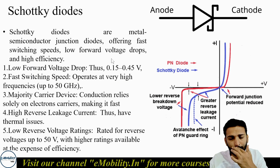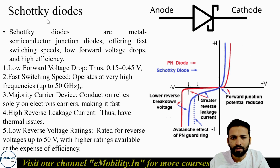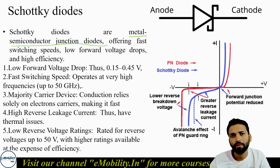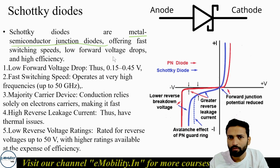Now, when coming to fast recovery, there is a special diode known as the Schottky diode. What is the difference with the Schottky diode? It is a metal-semiconductor junction diode offering a fast switching speed at a low forward voltage drop.